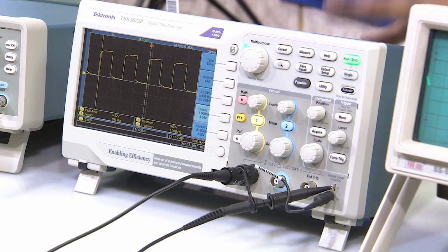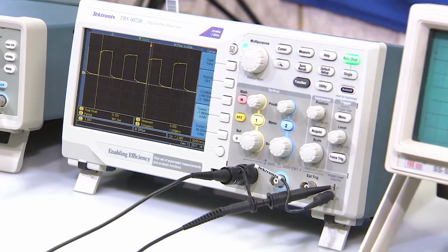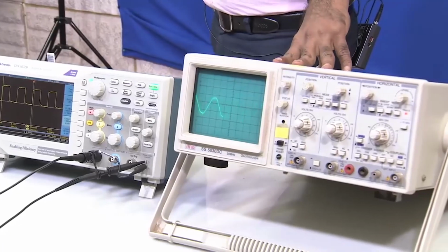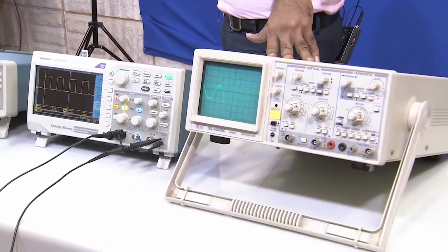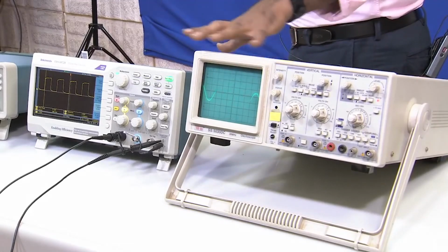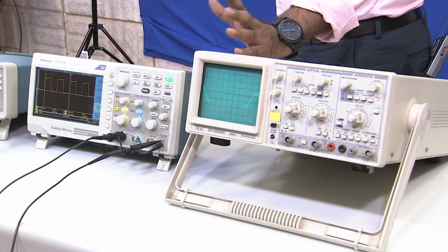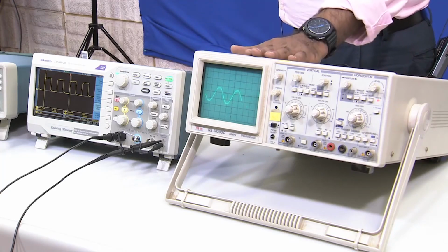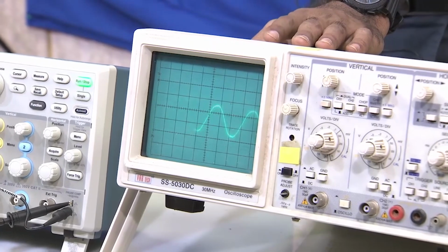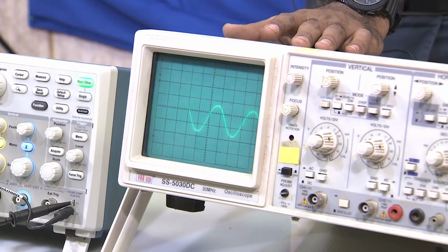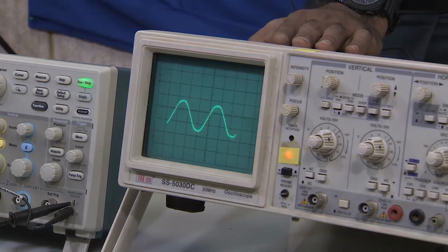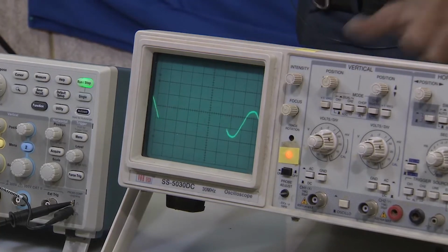Also, let us compare this digital oscilloscope with the CRO. Now this is your CRO, a cathode ray oscilloscope. In this you can see similar functions, but in a more crude way, alright. So, let us see what the functions are. First is the intensity and focus, because in a digital oscilloscope we use either LCD or LED, but here we are using the cathode ray tube. So, here we have to change the intensity and the focus.